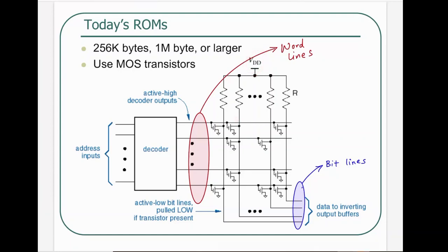If I was using a resistor, then every time my transistor is on and there is current flow, it is current passing through that resistor, which is going to be absorbing power. I do not want to use the resistor, right? Which is exactly why we did not construct our logic functions using NMOS transistors and a pull-up resistor. We did it in a complementary fashion with CMOS, where the pull-down network was NMOS and the pull-up network was PMOS. So that is huge energy savings. That's the reason. We could have used a pull-up resistor, but